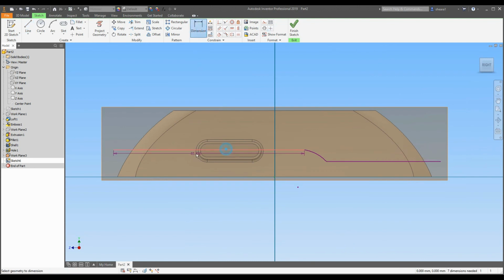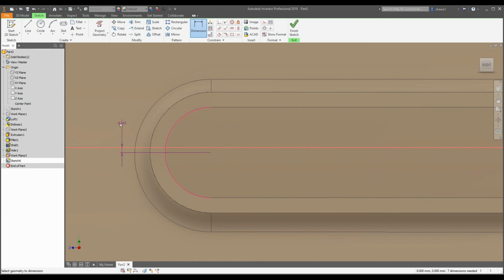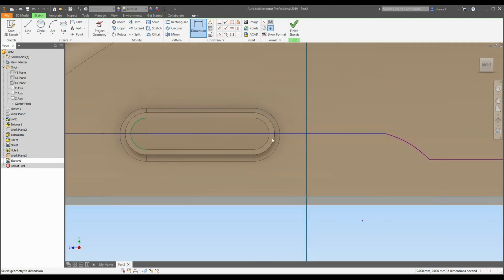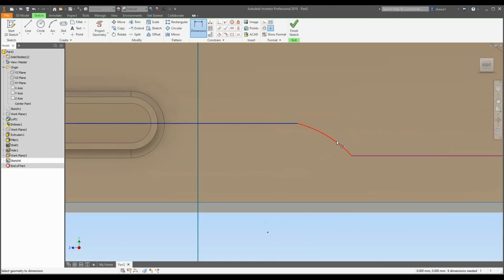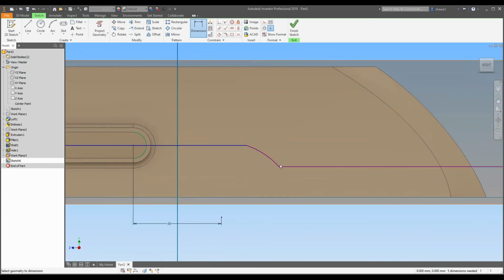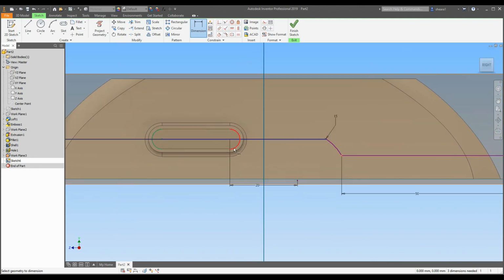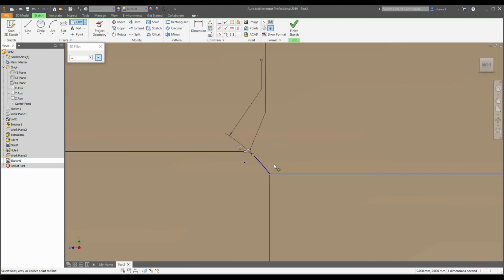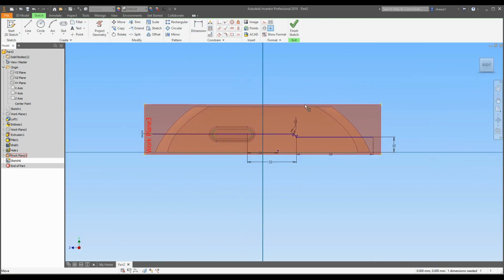However, we do want it to be fully constrained, just like everything always is. So I'm going to apply some dimensions to this. Let's say I want it to go directly through the center of the box here. You can apply dimensions that you think are fit until it looks somewhat reasonable to the way you want it to look. Once you've got a nice sketch, all smooth and cleaned up like this, all nice and blue, you can go ahead and click Finish Sketch.